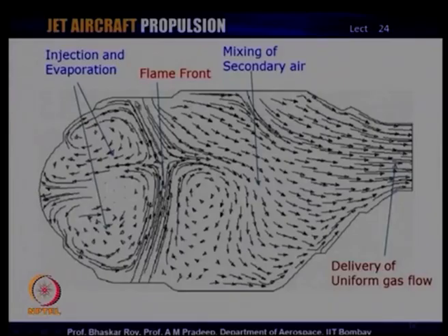Now, the flame front of course is the flame with which the ignited gas moves, and this moves at a speed which we call the flame speed, and it moves within a certain distance. At the end of that distance, the entire combustion process is over, and the flame has produced the combustion products, which then move away from the combustion zone, and a new flame front is already created.